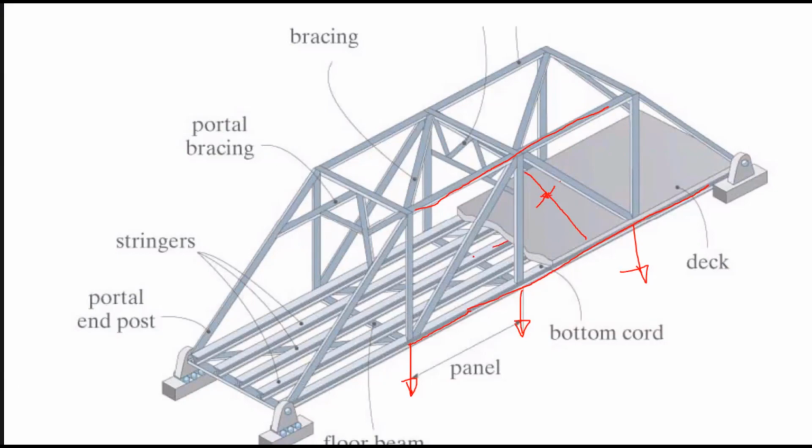It transfers to the longitudinal members. These longitudinal members aggregate the force. They go into the cross members, which go into the truss, and they carry the load. And you will see at the bottom, there are some inclined members also provided between these two trusses. Now let us see why they are there.